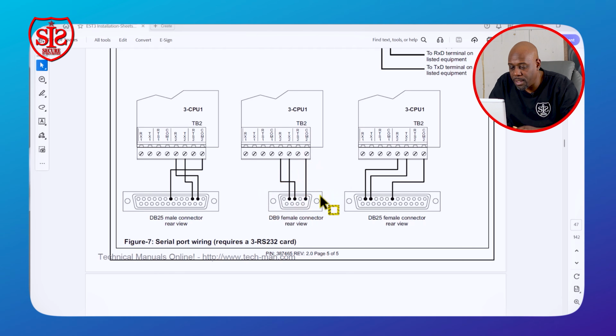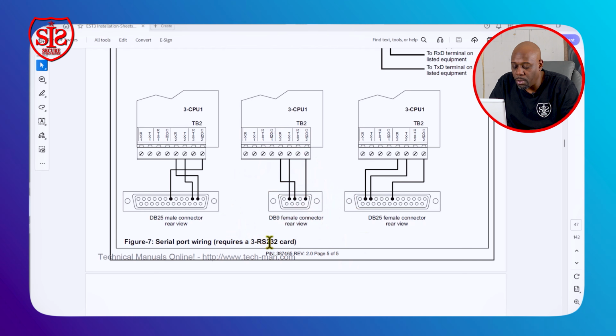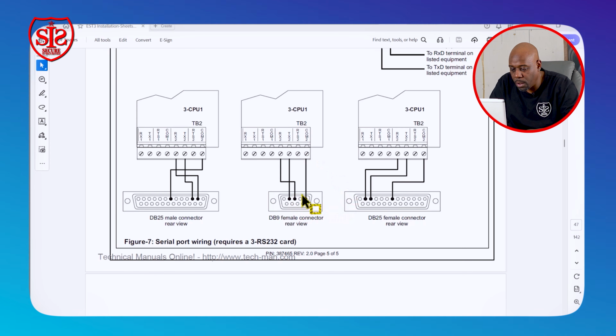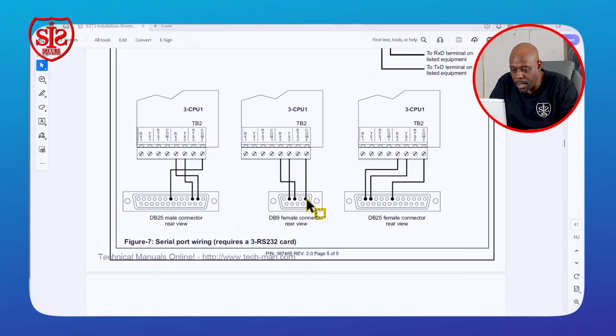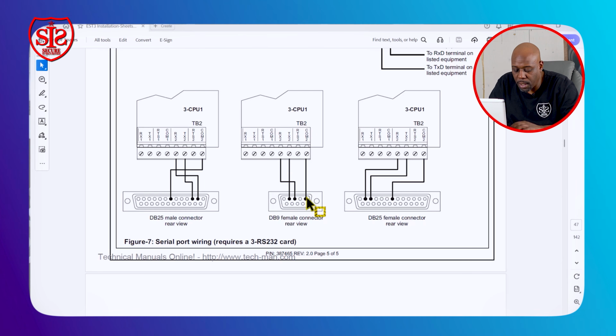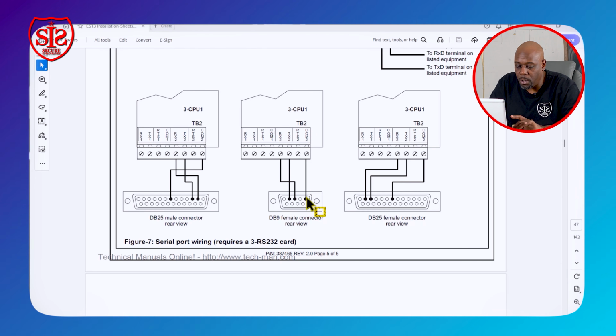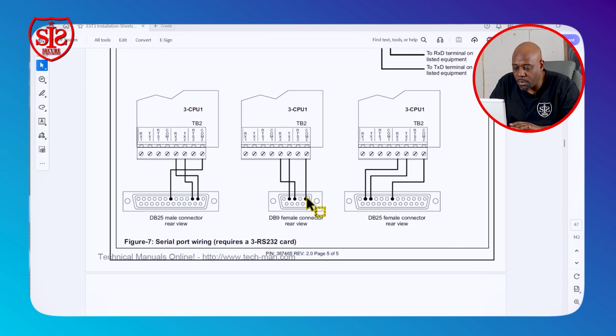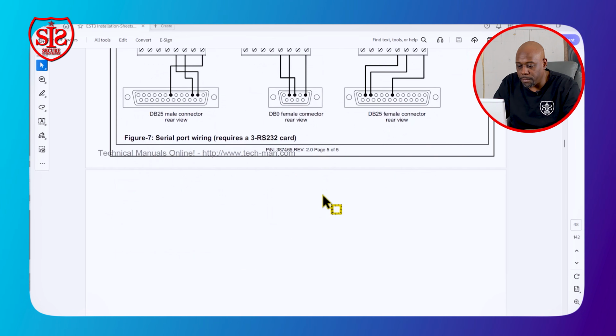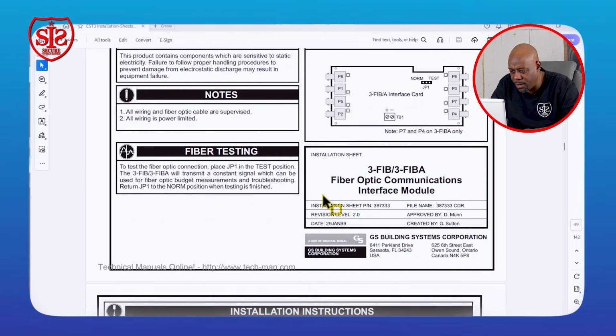9. And a good way to test this, this is a pro tip, if you want to test this to see if this actually worked, you can use a little piece of wire or jumper or something like that, short out the transmit and common while it's plugged into your laptop. You have Notepad open, and if you can actually type on the screen, then that means the cable is working. I know you guys are going to hit me up like, oh, what did you say, how do you do that again?